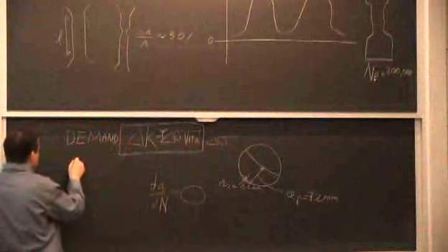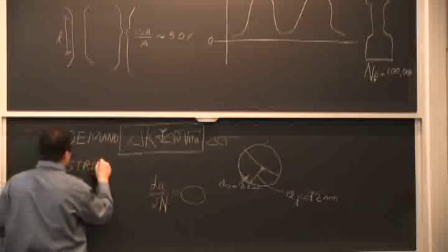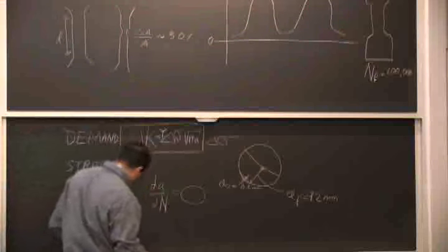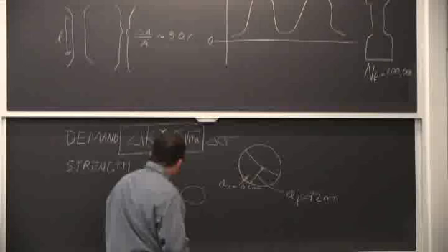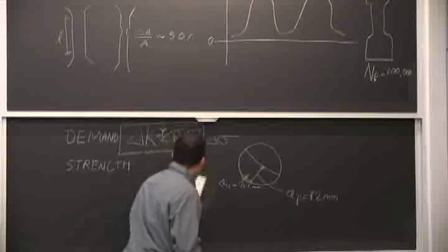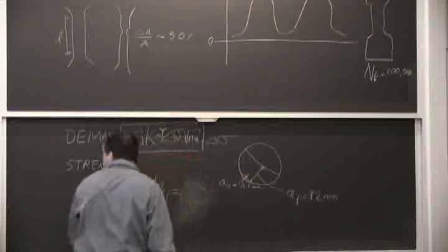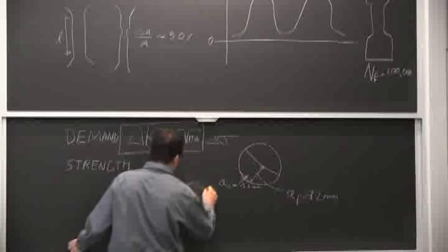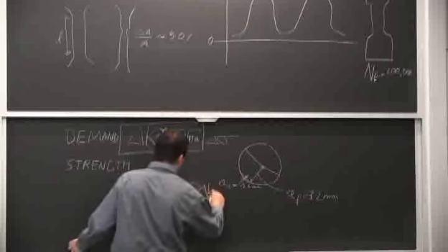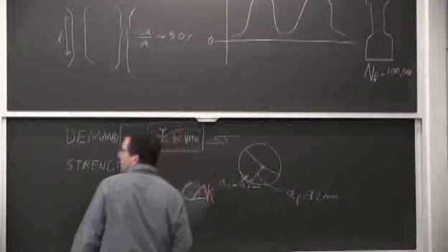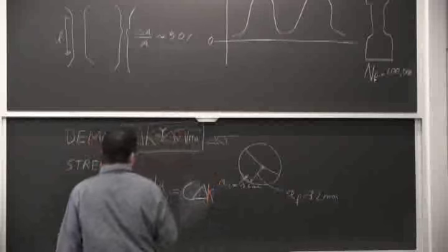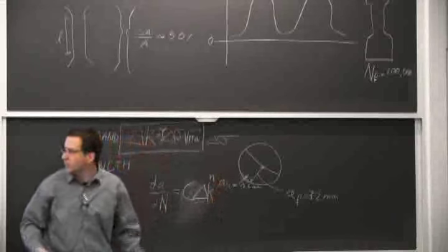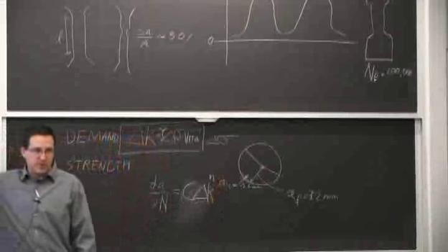And then we'll call the other one the strength, so we're not confused by it. So the strength, you C or Y, it depends. C, yeah, material constant. C delta K to a certain exponent n. Yeah, but this is not the same n as our strain hardening exponent. This is the n for that slope here on that specific plot. It's very different.